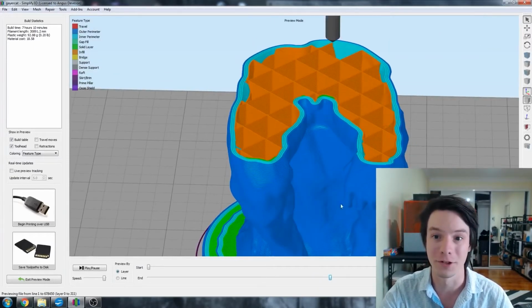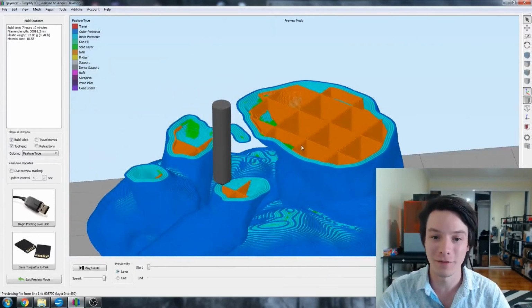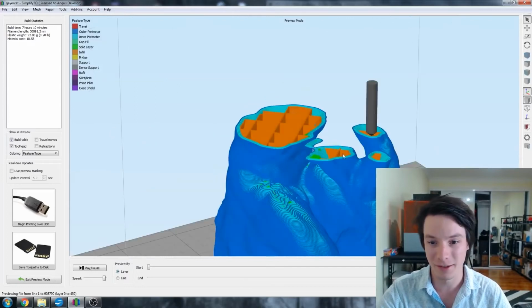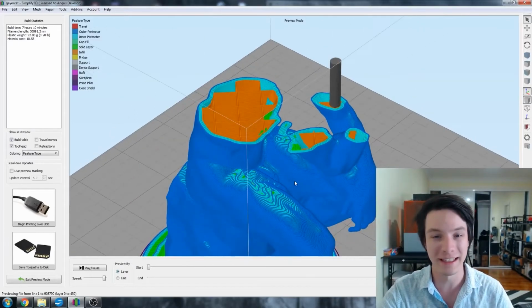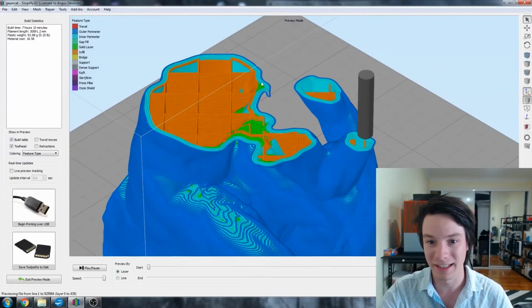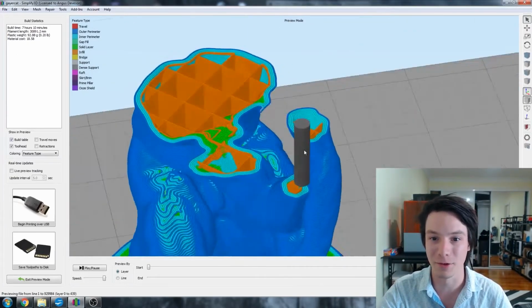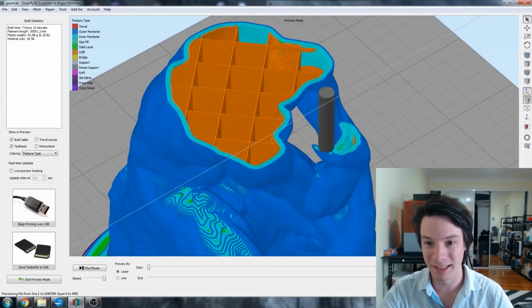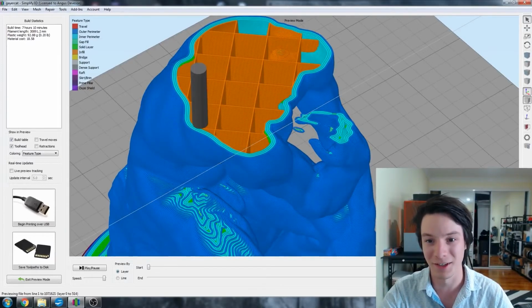So you need to decide, is it really important for me to have this overhang here? If so, am I going to be able to cut away these support systems? If not, do I really need to have these overhangs? Is there another way I can design this so I get the same aesthetic look without having to deal with these structures later?